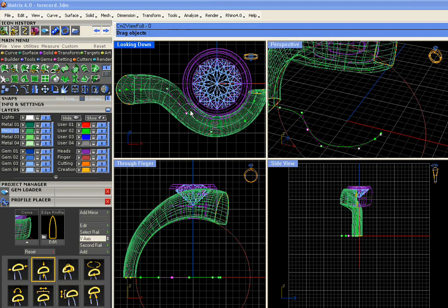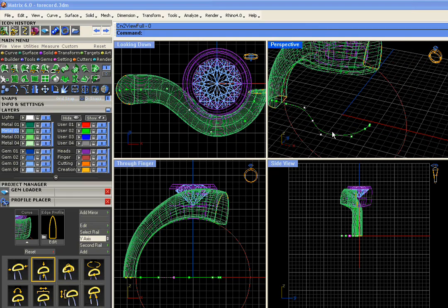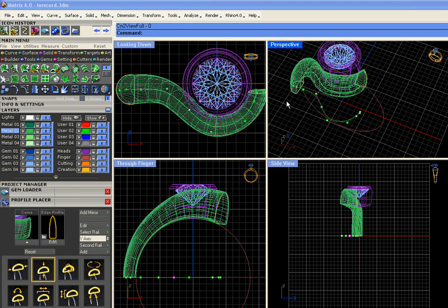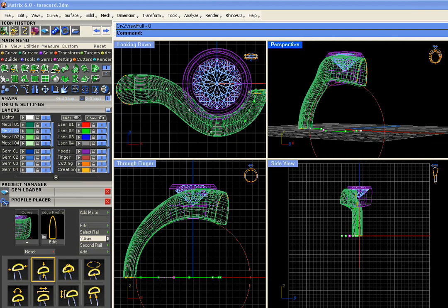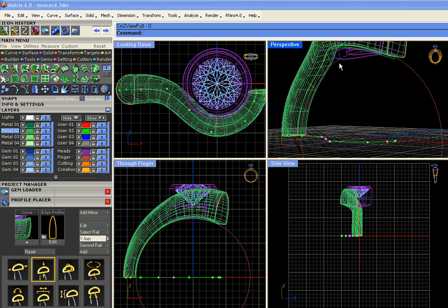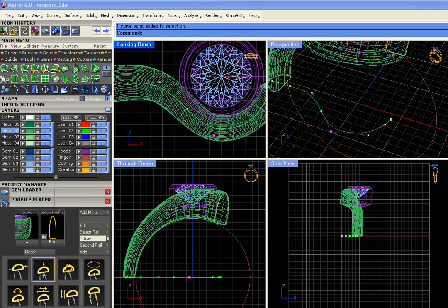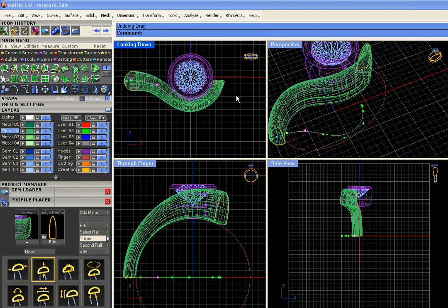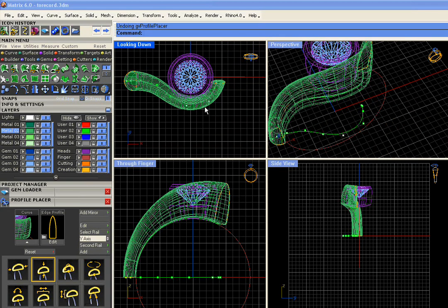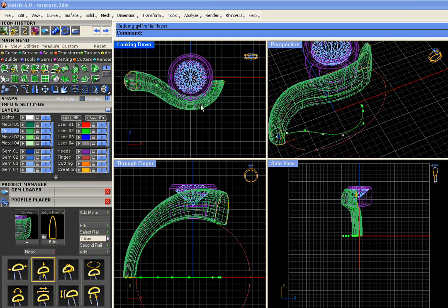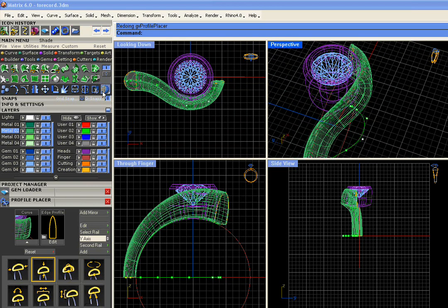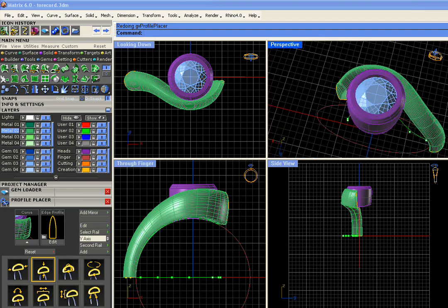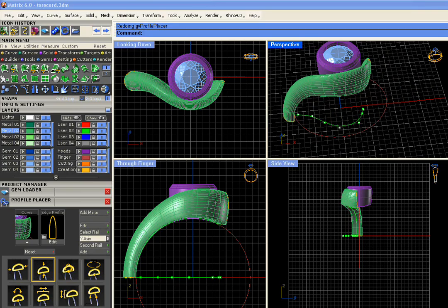We can get this to look any way we want. And that's the curve from Two Views history working together with the sweep history, because the sweep history knows its rail curve, this guy, and this guy has a memory of this curve. So in order to adjust him, we adjust the flat curve, which is much easier to change, which in turn edits the surface. And again, I'm just going to hit undo, undo, undo. I wanted to show you how you can move it, but I think I like my first one better. We can shade that up and make sure we love the results. Okay, and hit escape twice to turn off the control points down there.